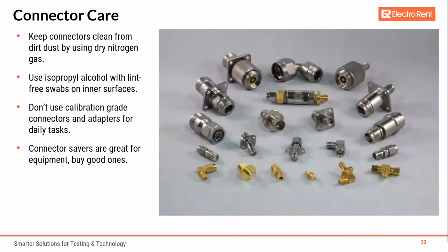So connectors come in various shapes and sizes and quality. It's recommended to use sources of canned air or nitrogen. Use lint-free swabs. Use isopropyl alcohol. Help prevent contaminant buildup by keeping your connector clean. Contaminants can follow the connector. They infect the mating connectors. Contaminants can cause damage to expensive equipment. Contaminants can cause discontinuities as well at high frequencies.